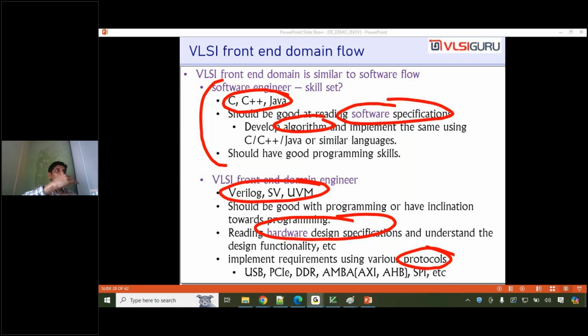Then we'll move on to what is a D flip-flop, what is a toggle flip-flop, how to write a Verilog code for that. What is the change we are doing? We are moving from combinational circuits to simple sequential. So when you move to sequential, what will come? Clock will come, reset will come. So there we'll introduce what is a clock, what is a reset, how to implement circuits with clock and reset, how to verify them.